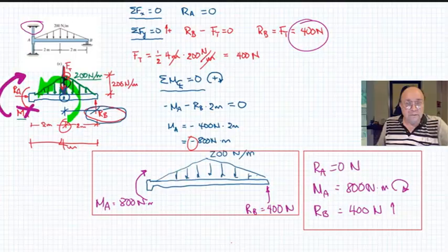Okay, so the procedure for making a free body diagram, steps have to be memorized. Basically, select your structure, then draw it completely isolated from everything else. Remove all the elements that are not included in your free body diagram. Every element that you erased was touching your structure.